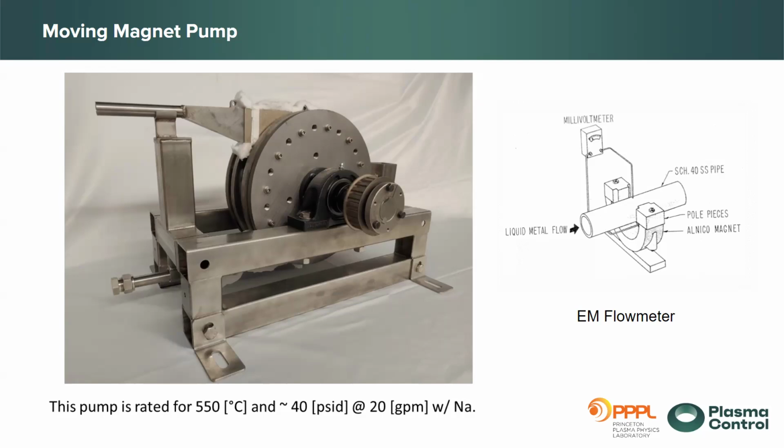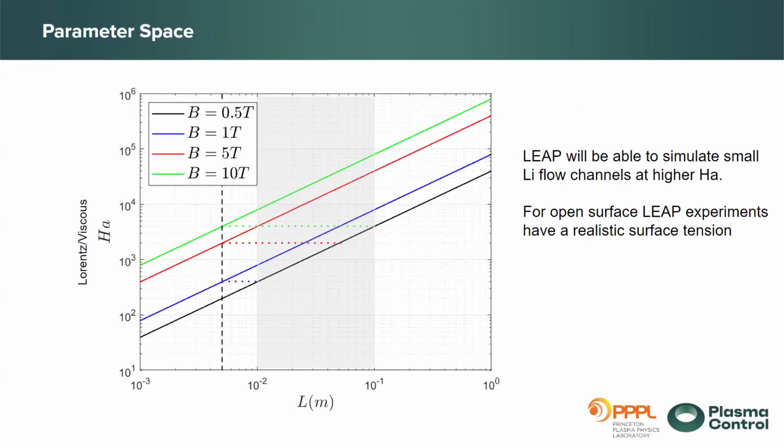But were you going to have a nitrogen scrubber? Good point. This is also for the secondary confinement. The first confinement will keep the nitrogen concentration below 1 ppm or so. But adding a nitrogen scrubber is really expensive. Yeah, you don't need that unless, for the whole glove room, it would be very expensive. What's the environment in the inner glove room again? The inner part that's around all this stuff. The first, that's a vacuum.